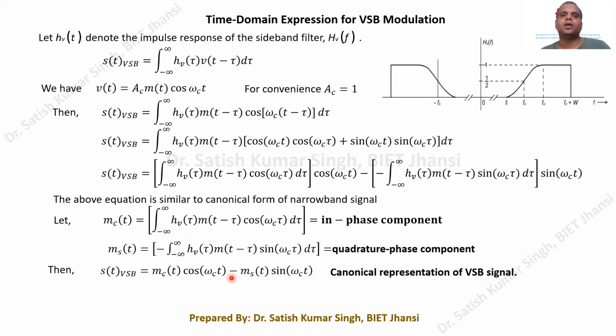Because DSBSC and SSBSC are both not suitable for transmission of the video signal, we generally send the video signal through the VSB modulation technique. We choose a particular carrier and send the complete part of one sideband, the upper sideband, while a little part of the lower sideband is also retained.